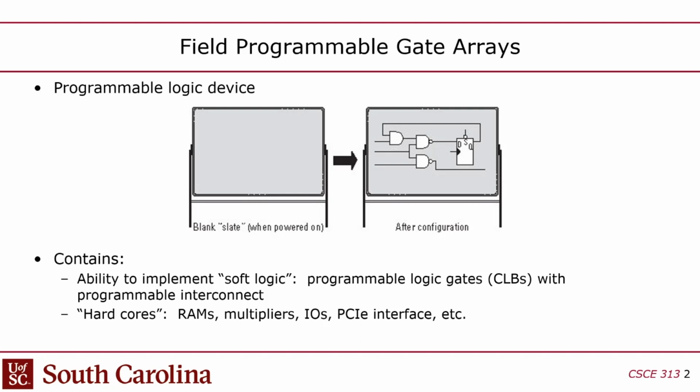But if you send a specific bit pattern in, it unlocks the ability to get your hands inside that chip. It's basically like JTAG. Rather than just emptying whatever's in the registers, with the reset it would let you go into probably a state machine. Yeah, well, it lets you freeze the CPU, which is the big thing for debugging. You want to be able to freeze it.